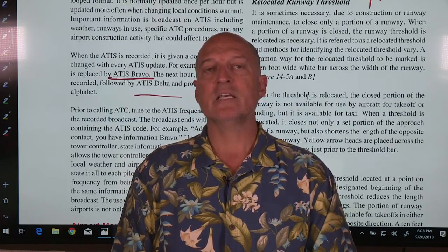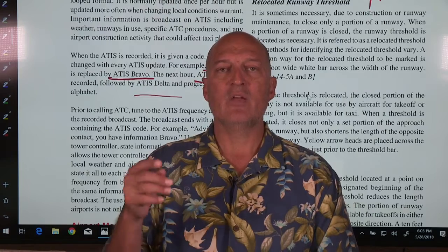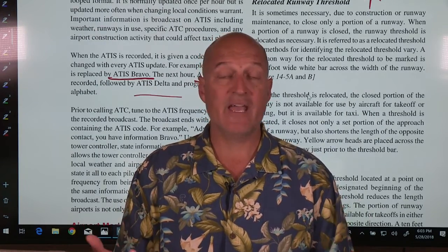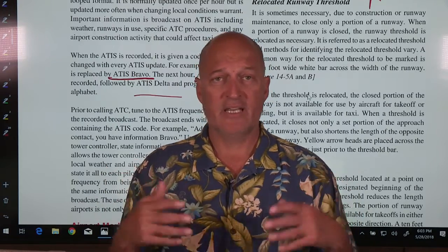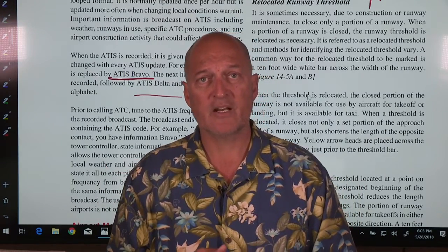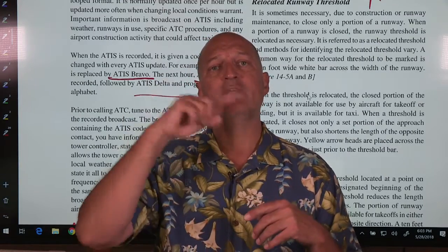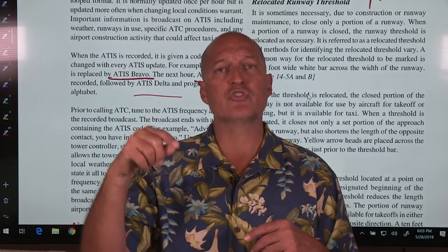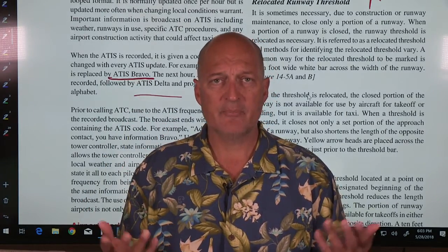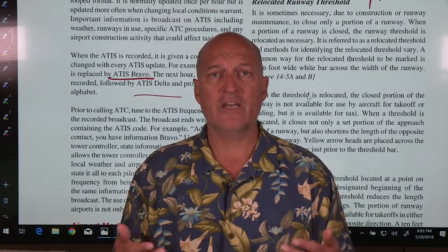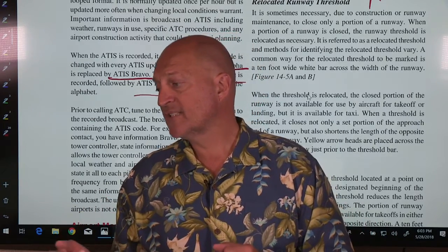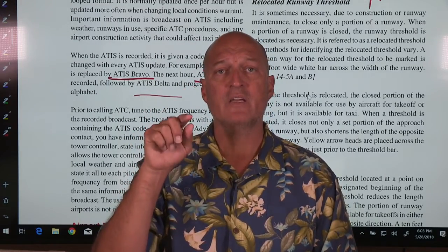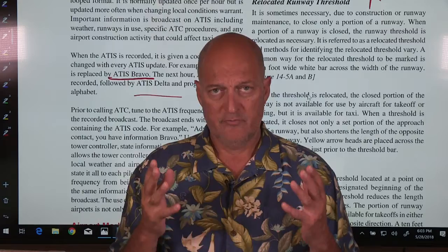And in some cases, Aspen Approach, if you contact them or they contact you, they will ask if you have the information, and you may have to tell them, listen, I'm trying to get it, but the communications keep getting garbled. That's if you're on flight following, and Denver Center may hand you off to Albuquerque Approach early, and you may not have had a chance to pick up the weather yet, so you just let them know that you'll get it when able. So that's it. You get it over the radio, and each airport has their own specific weather frequency.